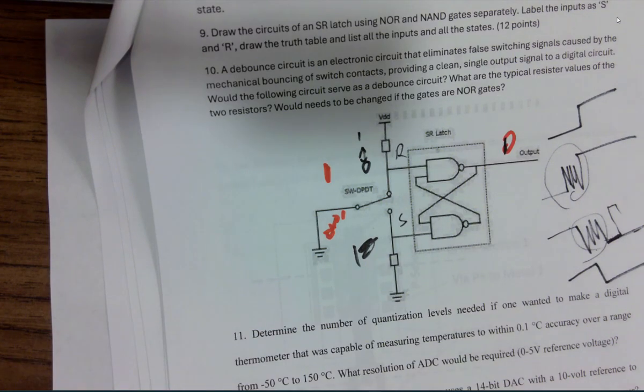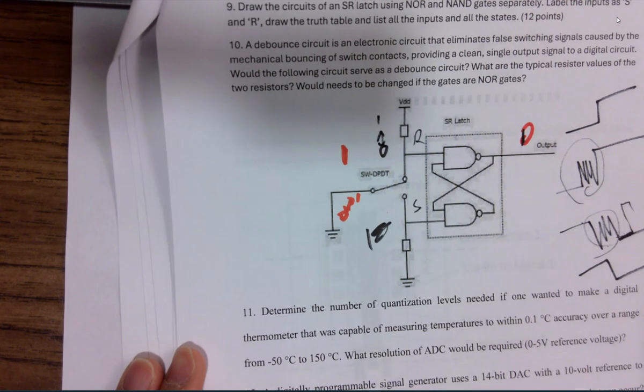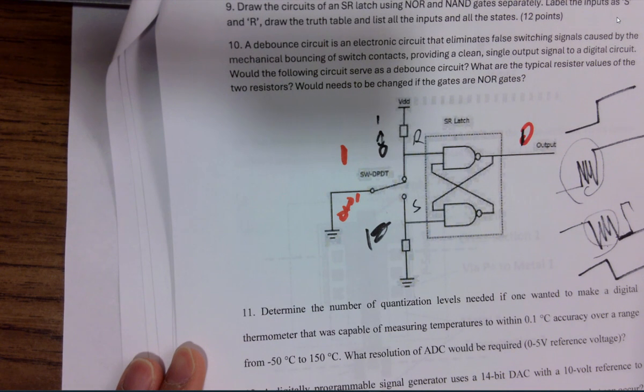It could be a NOR gate based debouncing circuit, and there will be different pull ups and pull downs and different signals, just to let you know. You need to be able to fix it. Yeah, so that bottom section is a VDD instead of ground, correct? For this one, yeah. I won't tell you. I think that would make more sense. That's a good question though. That's a question for you guys during the exam. Okay, study this a little bit and draw a NOR gate version and figure that out as well.